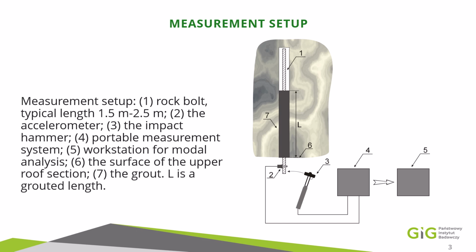A rock bolt may be treated as an oscillator, and different lengths and position of grouting change its form, with different border conditions, and since it changes its modal parameters. By proper extraction of these modal parameters, from which natural frequency is seen as more crucial, the proper identification of the position of discontinuity is possible.